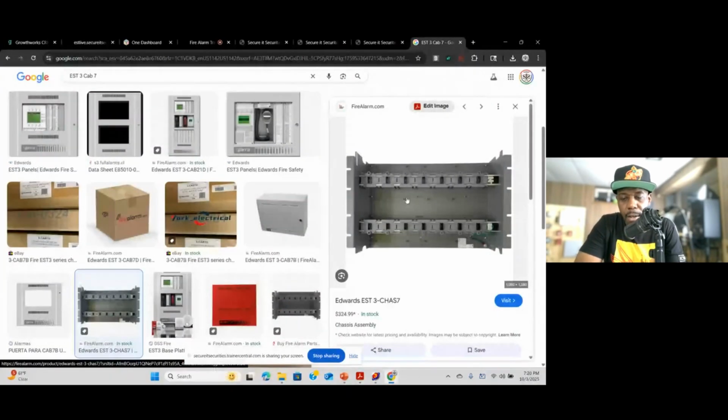Inside of, you would have to know this, especially if you'll probably be in the field. Let's say you're in the field, looking at the fire alarm control panel, and it's just a small system. This is what the bay looks like behind it. So these first 4 slots will be the CPU. Then this next slot right here will be your power supply. Then every card after that can be whatever.